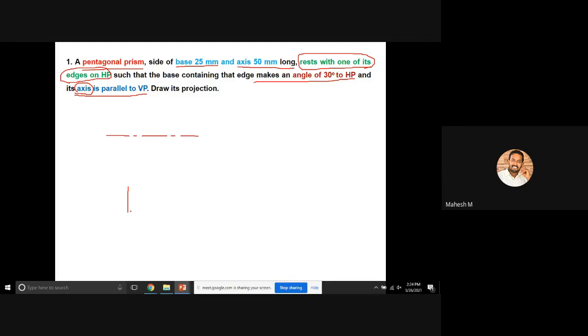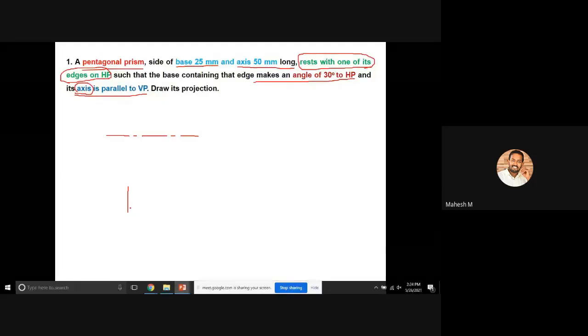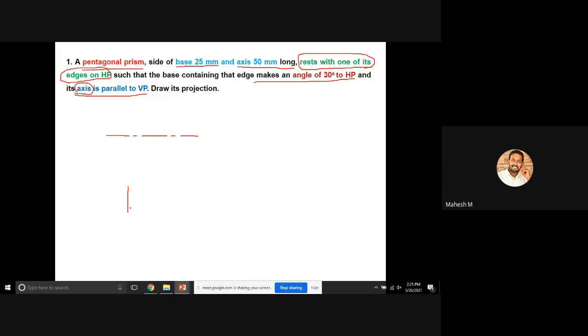In this solid condition, please use the edge exactly at the right side of this problem. If you want to create a pentagon with the edge on the left side, you will be able to do it, but the condition will be a little bit different. Okay, so clear? If it is a plane, you have to draw this pentagon exactly with the edges on the left side. So here in solids, you have to draw a pentagon with an edge exactly at the right side.